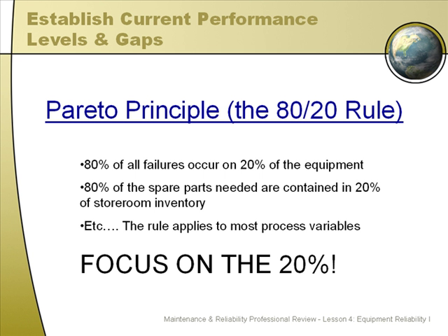Now do the math. We just cut that list 3 times, from 10,000 down to 80 pieces of equipment. Now if you take that and compound it and calculate the fact that you're getting 80% of the value out of each of those steps, we're reducing our impact on the process every time we take some equipment out, but not that badly. After 3 cuts, we're down to a 1-page list of equipment. If you make those 80 pieces of equipment reliable and eliminate their chronic failures, you will cut your maintenance work by 51%. 51% of the equipment failures in your facility will be gone. Do the math. It's surprising, isn't it?